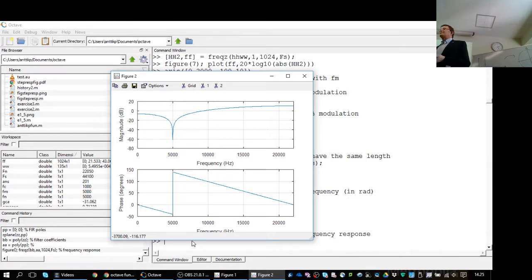And we are not arbitrarily putting poles, but we can also define what is our bandwidth. So basically, we can also set the half band parameter, which is the minus 3 dB width for this filter, and in this case, let's use 100 hertz. Sounds just about as good as, well, let's put it 200 hertz. It looks better on display. Of course, how wide you want that filter depends on the application where it's going to be used.